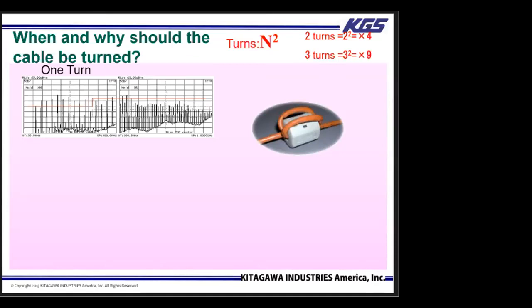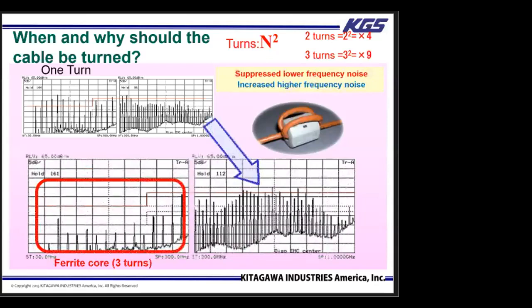We tested with 3 turns, and this graph shows the test results. Turns can have a very powerful effect for lower frequencies, as you can see here. Basically, the noise level is reduced. However, it is not as effective for frequencies over 200 megahertz. In this test, you can see the noise emissions increase at higher frequencies.